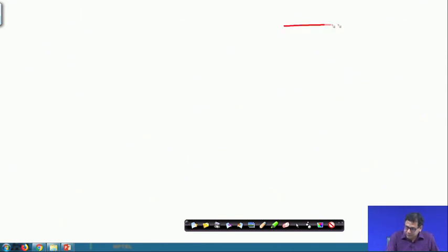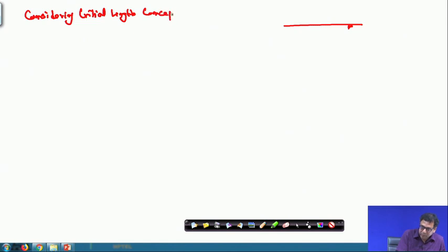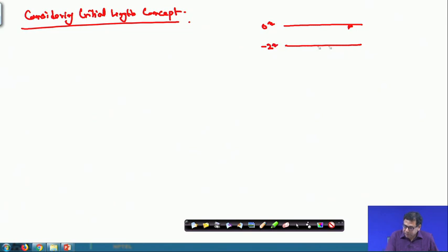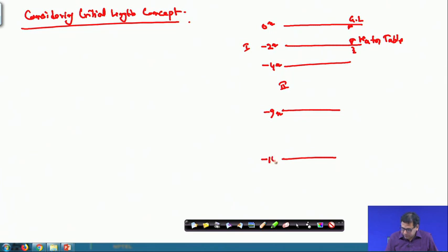The same ground level is 0 meter, this is minus 2 meter where it is the water table, and here this is 4 meter the first layer, this is minus 9 meter the second layer, and minus 14 meter third layer. Up to 14 meter this pile is resting.